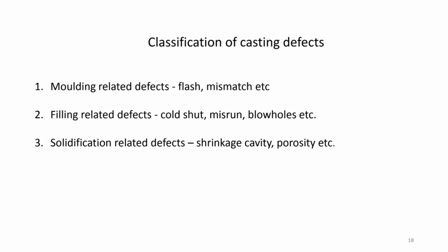Next is filling related defects. If your material cools very fast, then it might not reach all the places. In some complex areas, edges or corners, they might not get filled properly. So these are cold shut, misruns, and blowholes, etc.